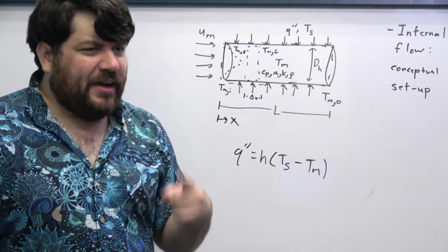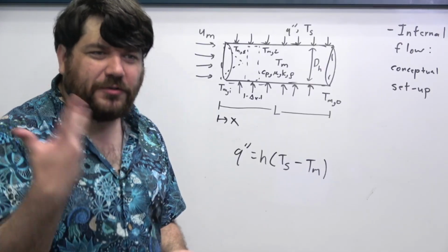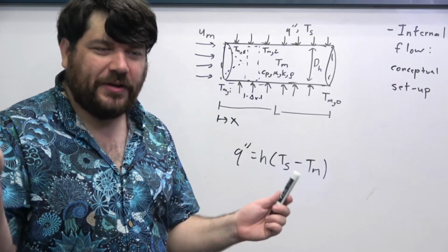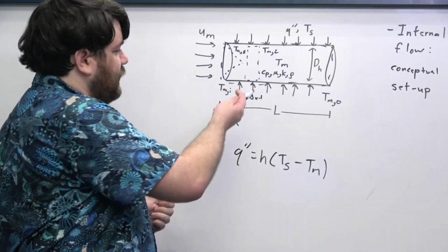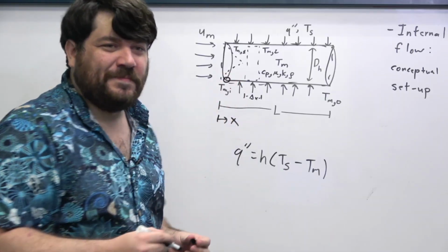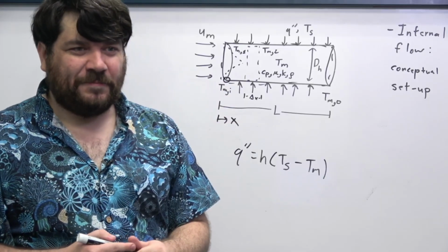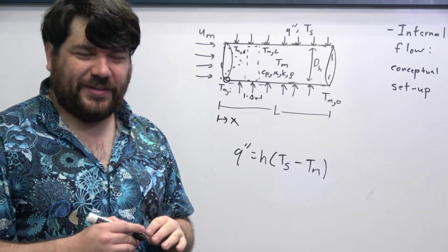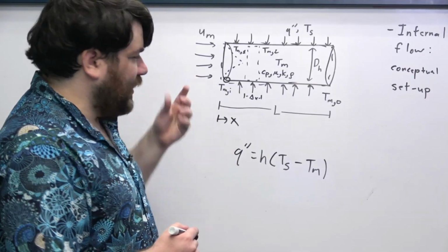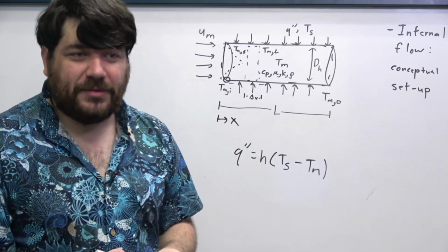So how does that flow change? Well, remember that the no-slip condition we considered for flow past flat plates applies at this little chunk of pipe inlet. If we zoom in hard enough, you can imagine that the curvature goes away, and from the microscopic perspective of the fluid, this is just a tiny flat plate.